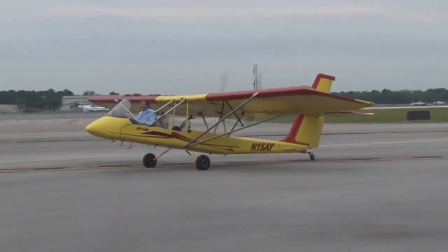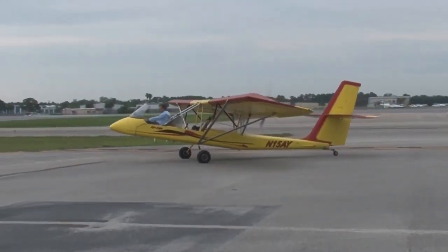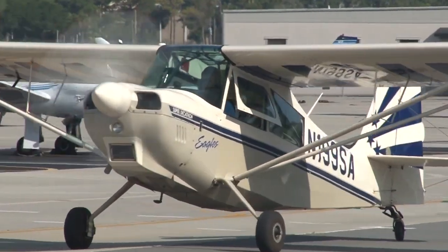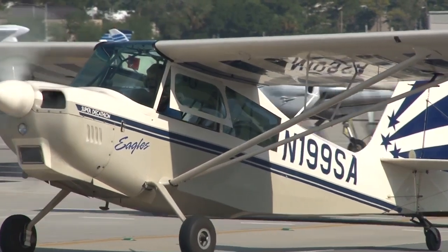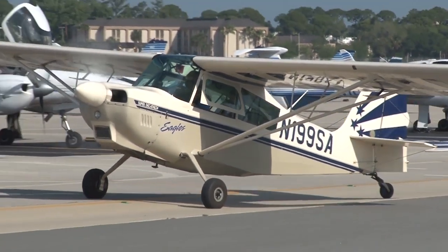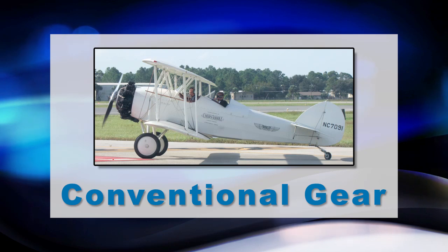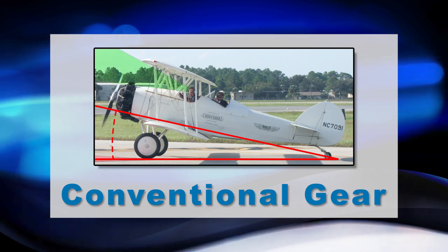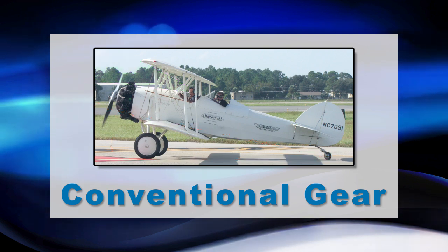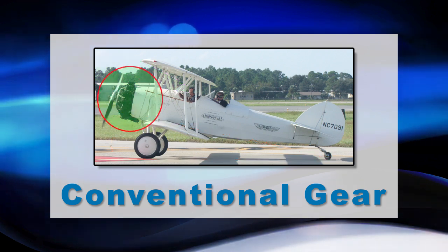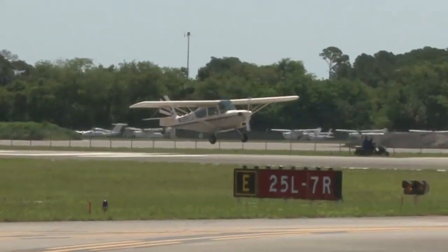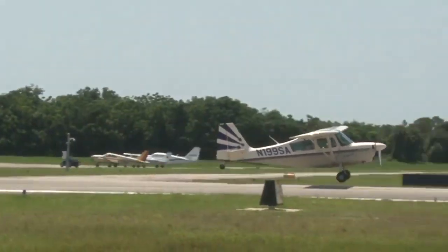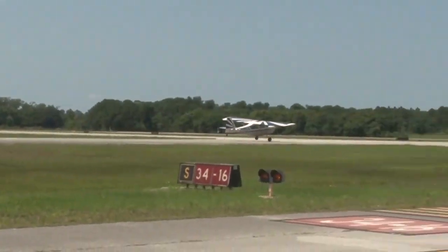Conventional gear, on the other hand, is the older style that was popular a few decades ago. Similar to before, 2 main wheels are typically situated under the wings, but the 3rd wheel is located under the airplane's tail. This results in the tail of the plane being very close to the ground, while the front of the airplane sits much higher. This obstructs the pilot's forward view because of the airplane's nose-high attitude. However, it does allow for larger engines and propellers to be installed on the aircraft. This setup is also the less stable of the 2, making landings more difficult, especially in a crosswind.